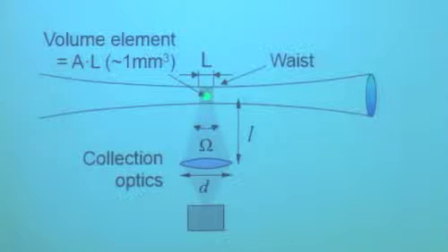That means that the signal that you're looking at comes from a small region of space that corresponds to the overlapping volumes of the illumination optics and the collection optics. So assuming there's not any competing radiation from elsewhere in the collection of this lens, the signal comes from what we'll call a point. A point could be small, could be big, and it doesn't have to be 90 degrees, but it typically is. So that means that there's a mechanism to make a spatially resolved measurement, which you might want if you're studying a flow that's spatially non-uniform. Now this is going to come at a price, and you'll see what the price is. But this is a huge advantage for certain situations where you really want to study the spatial structure of the flow.